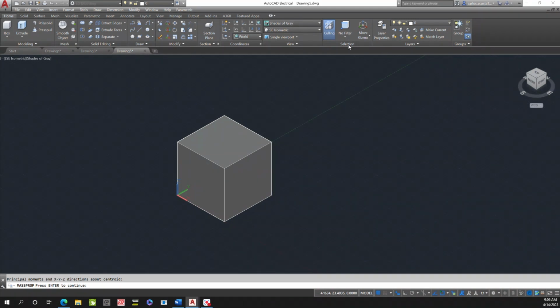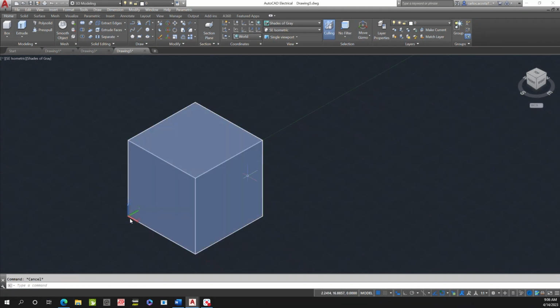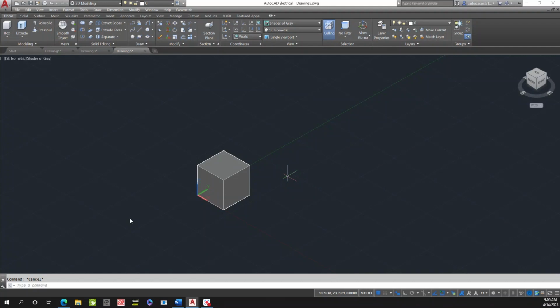Say you wanted to create another shape. Let's go ahead and do a circle, and you can just put it wherever you want. So let's say 25 and 25, and we're going to give a radius of 10 inches. Well, that's pretty big, so let's say 2 inches, and then press Pull and 10. So these two objects now are on the same plane, but they're independent objects. Okay.